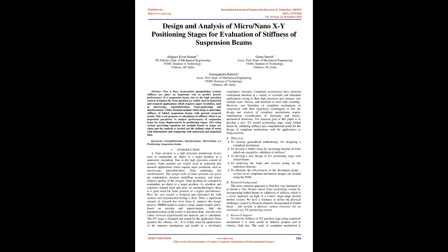The XY stage is designed and tested for nano-positioner applications like robotics, etc. It is widely used for optimization of the structure mechanism and results in a distributed compliance structure. Compliant mechanisms have attracted widespread attention in a variety of scientific and industrial applications owing to their high precision and compact size without wear, friction, and backlash, or need little assembly. However, one limitation of compliant mechanisms in comparison with their rigid body counterparts is that the design and analysis of compliant mechanisms require simultaneous consideration of kinematic and elastic mechanical behaviors.